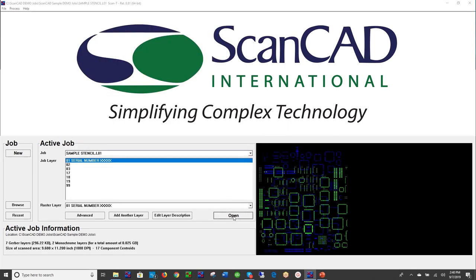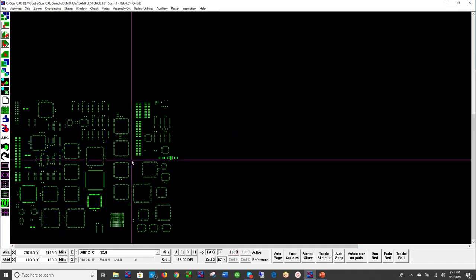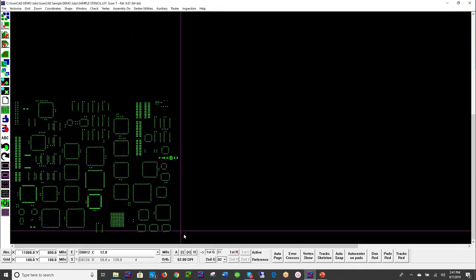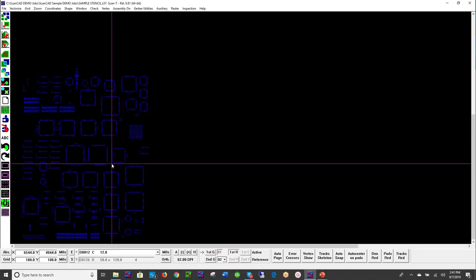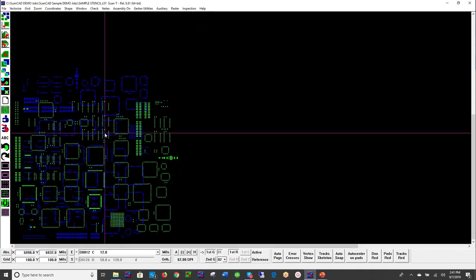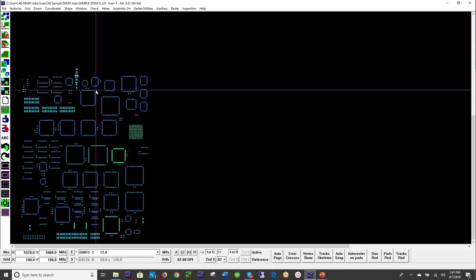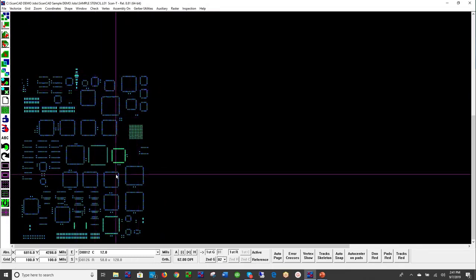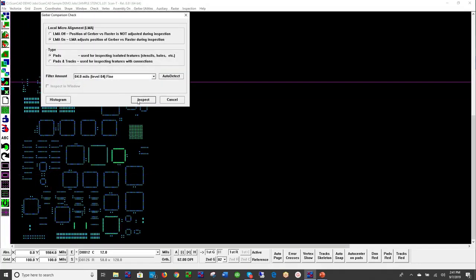And again, I'll show you more of the process now. The way the system works is you first import the CAD data in green. You next scan the part, in this case monochrome, using a backlight. And now we overlay. Now I just want to share with you, use these icons here, and this function here automatically flips and rotates to put the CAD data on top of the part. Okay? We then are permitted to perform an inspection.